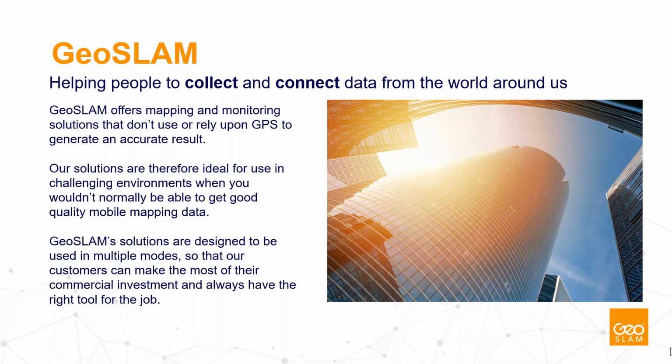And that's what we're using when we're creating the trajectories, and we're creating these 3D maps. We're using our SLAM as the basis for that, and as the structure of all of the data. So we're not being reliant on GPS or having a strong signal connection to the GPS. And so I feel that it's a key point to all of the GeoSLAM products. And so with that in mind, you can see why we've been so successful in these challenging environments where you wouldn't normally be able to get good quality mapping data.